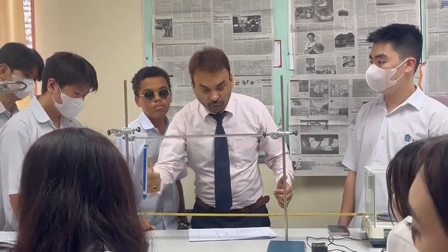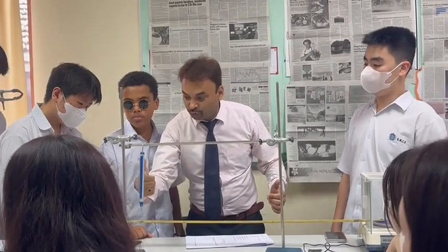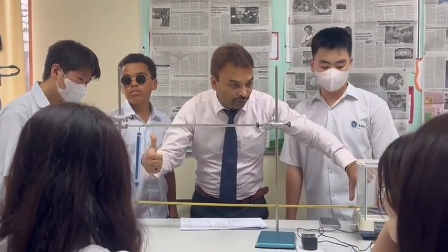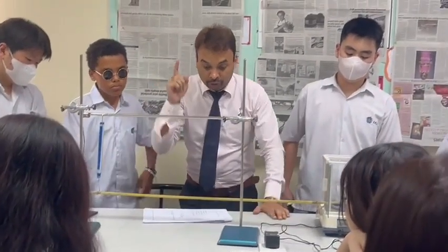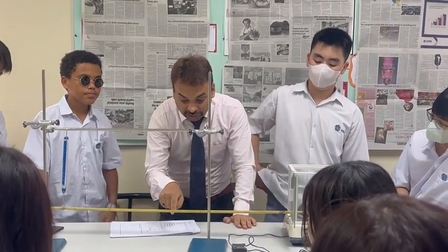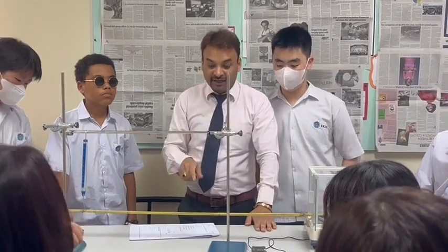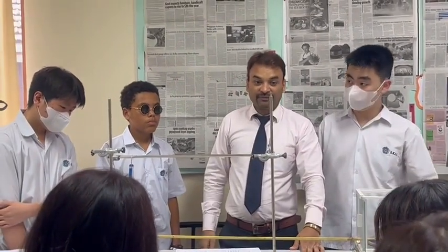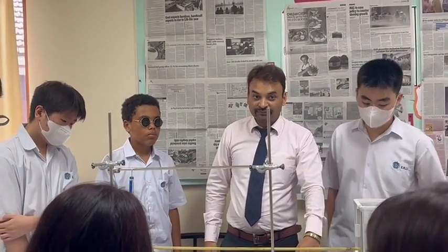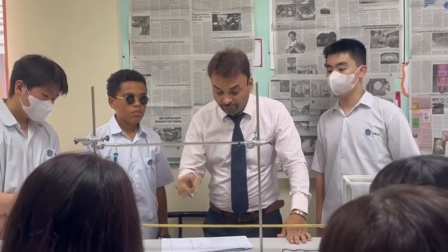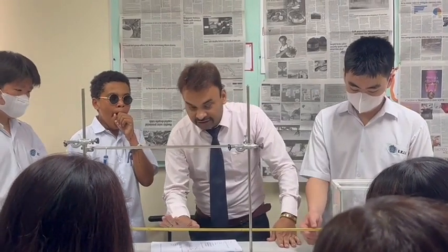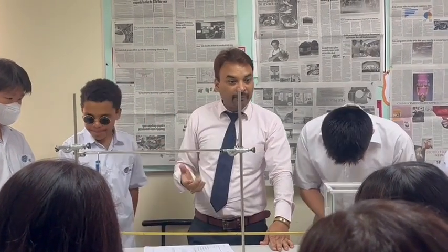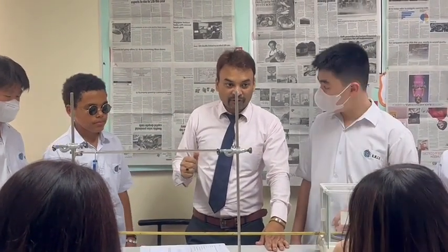There is an upward force at 90 centimeter, which is 40 Newton, and there is a downward force at the pivot, which is 52.17 Newton. But you have to find the downward force at the center, exactly at 50. How will you calculate? Or if they ask you to find the force at 40 centimeter, 30, 60, or 70, any random position, how will you find it?